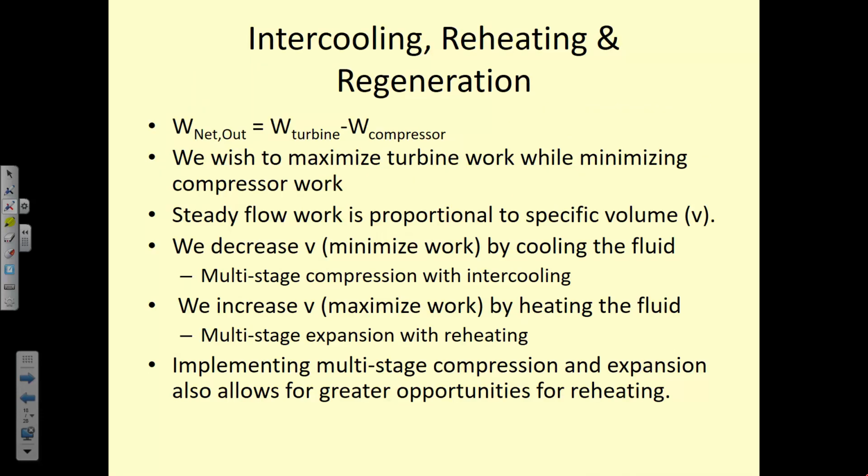Okay, oh, I had a whole other slide. Okay, so we can do regeneration, which allows us again to recoup some of the heat from the exhaust to preheat our gases as they come into the turbine, or into the combustion chamber and then into the turbine. So that reduces the amount of fuel we have to burn in order to drive the turbine, which then increases our thermal efficiency.